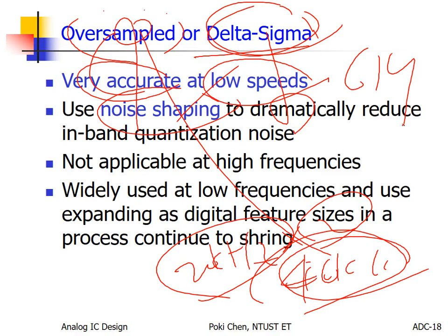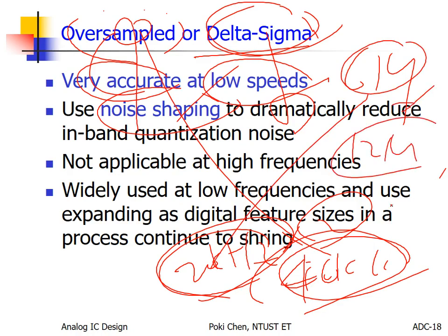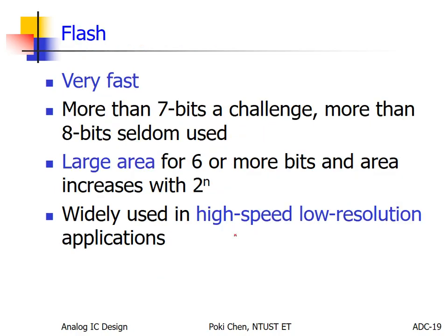They are totally different in order, from 20 kilohertz to 6 megahertz, times 2. An image ADC needs to operate higher than 12 megahertz. It's really hard to apply delta sigma here. This is too high, and this is the major reason why delta sigma is still mainly applied to audio signals, because audio needs only 20 kilohertz.